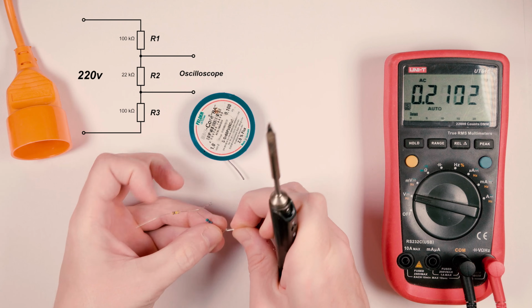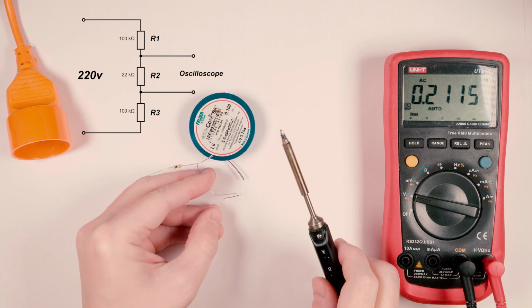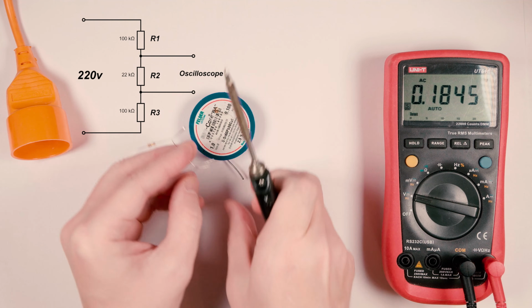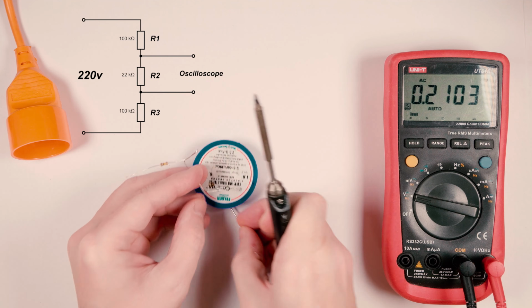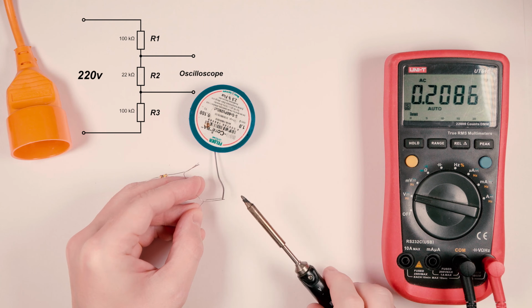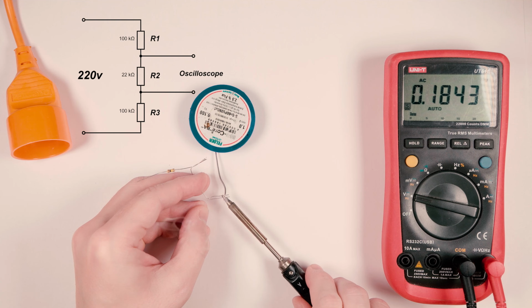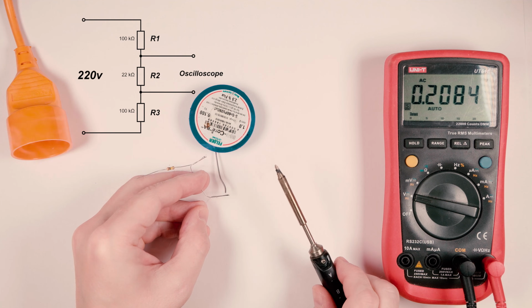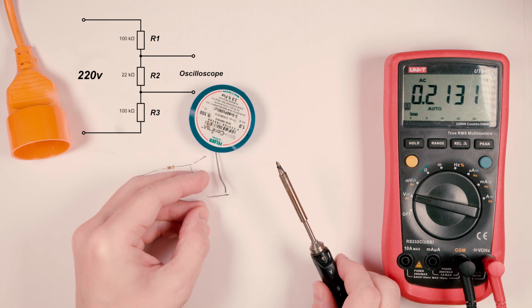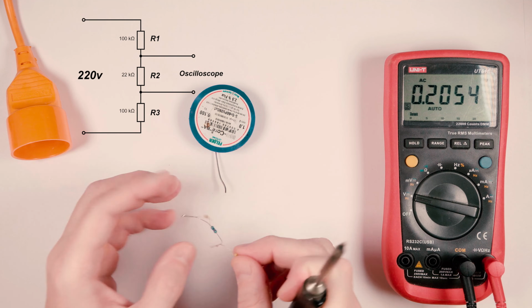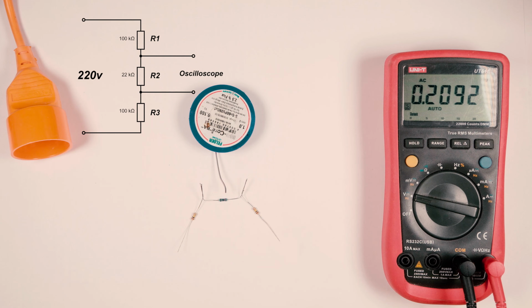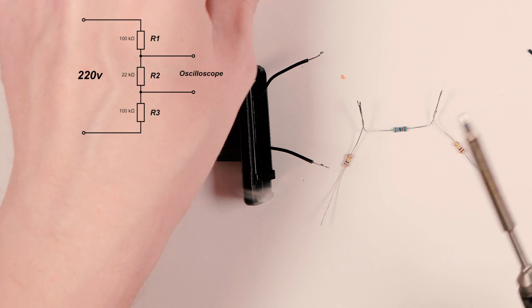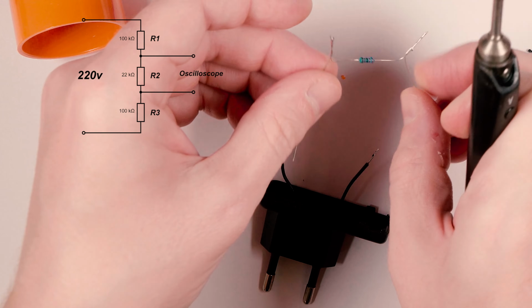3 resistors are needed to obtain a relative decoupling of the output from the input, that is, to ensure the safety of the experiment. If it turns out that the common wire in the oscilloscope breaks through to the phase line, nothing terrible will happen, since the voltage will simply drop across the resistor. Ideally, we should have used 99K as R1 and R3, but I don't have such parts at hand. This is where the case from an old mobile phone charger comes in handy.